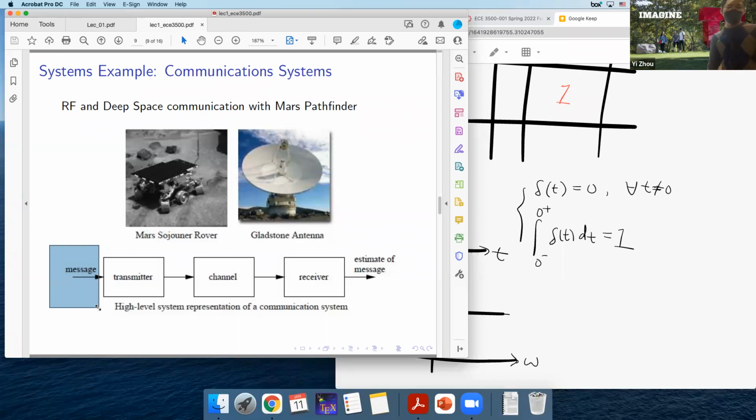The most straightforward way is to repeat the same message multiple times. Right? Instead of sending 1 or 0 once, you send it 100 times, and hopefully less than 50% of them will be distorted. And at the receiver side, you can do a majority vote and decode the original message.